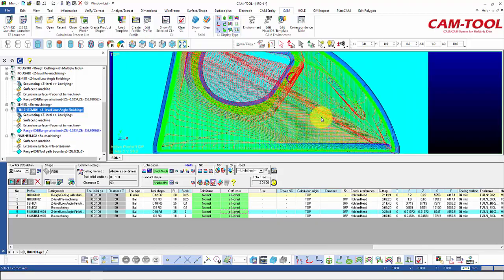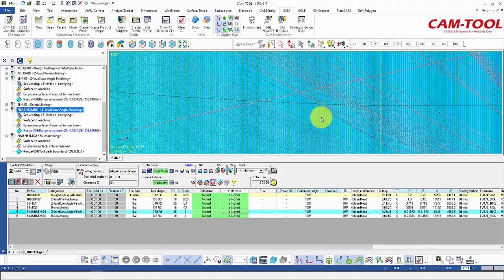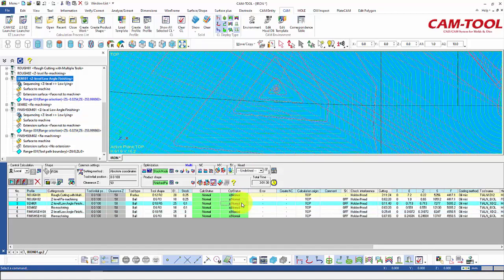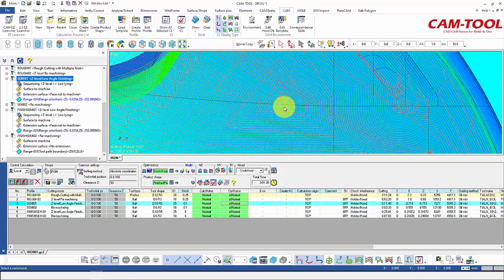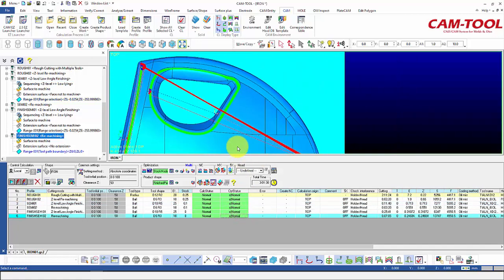Zooming in on the 10mm finisher, you can see that the scanning line is going back and forth across a low-lying area, where in our semi process, for the low angle, you can see it collapsing in based on the geometry of the part. We can double-click on the op status of the new remachining toolpath to see what it looks like.